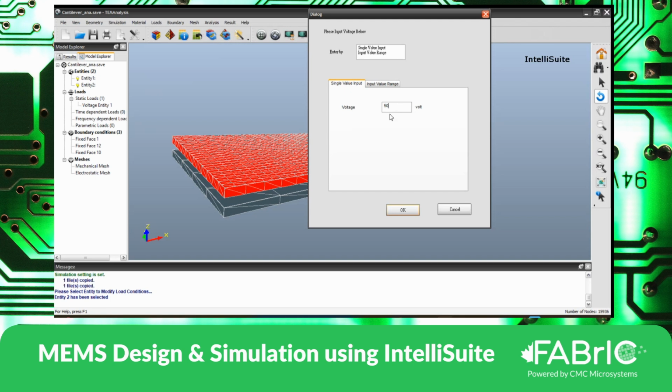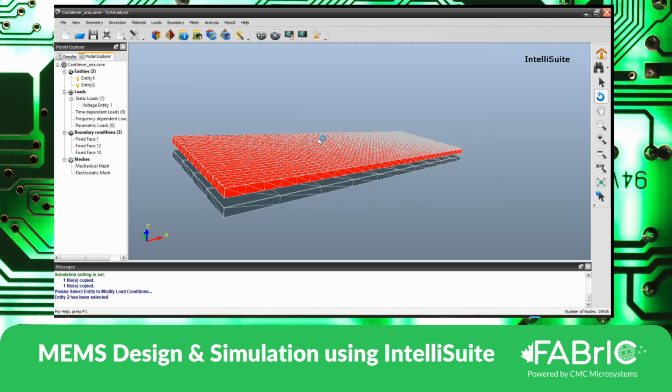Input value range, 0 to 50 volts in the increment of 10. I'm just choosing 10 because of the interest in time. So now it performs a simulation from 0 volts, checks the deformation, 10 volts, checks the deformation, 20 volts, checks the deformation, and up to 50 volts, the simulation keeps running in the iterative mode. So click OK.